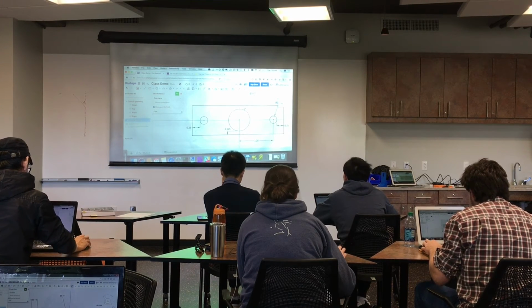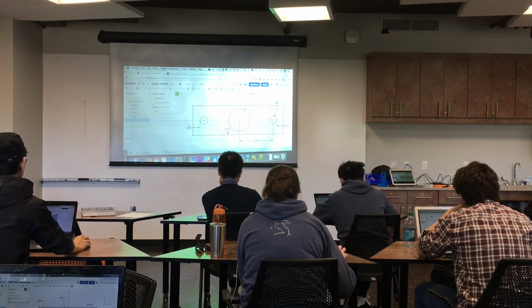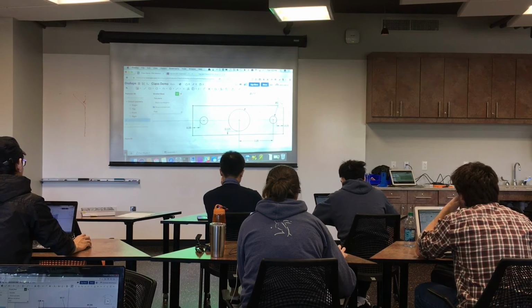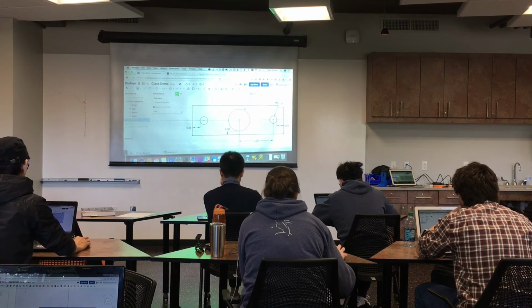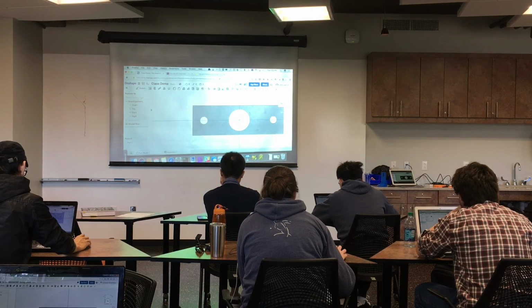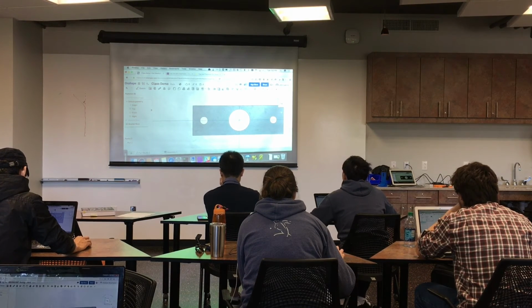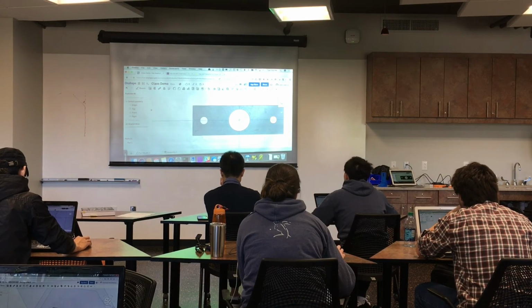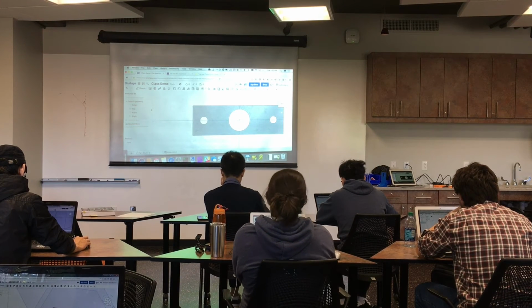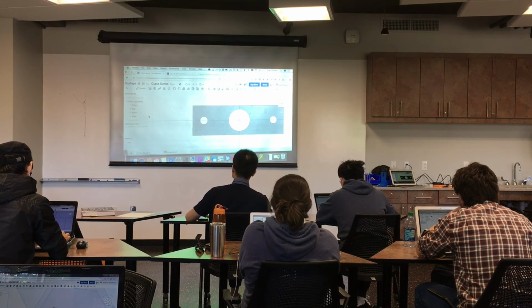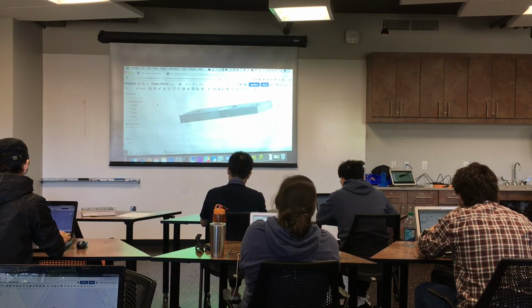All right. So now everything is fully constrained. The entire sketch is black, so we're good to go. And you click the check mark. Everybody have that? Yeah? Okay. So now we have something that looks a little bit more like our part.